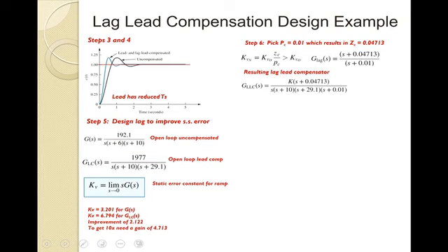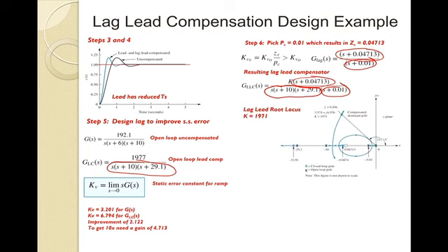Okay, so our resulting compensator is, notice in the denominator, right there, that's what we have here. That's basically for our lead, and then here's our lag term right there, and then we have our lag zero right there. So then I just have a value of k that I can change, so that's our lag-lead compensator. And then what I can do is, again, vary my value of k to get my desired dominant pole on my 20% damping line that I have here.